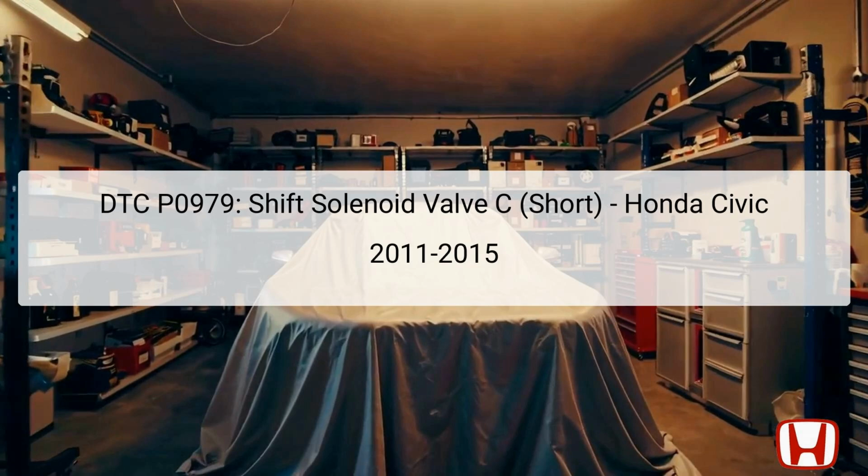The shift solenoid valve is a crucial component in the vehicle's transmission system. It controls the flow of transmission fluid, which is vital for shifting gears properly. When this DTC is triggered, it indicates a problem with the electrical circuit related to the shift solenoid valve C, and it's important to note that the issue is not mechanical but electrical. This issue could lead to transmission performance problems. Therefore, timely diagnostics and repairs are essential to maintain safe operation of the vehicle.